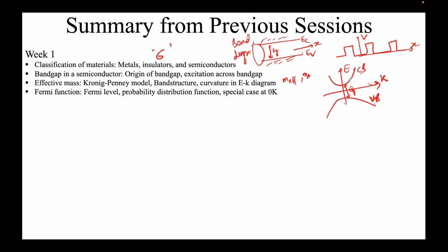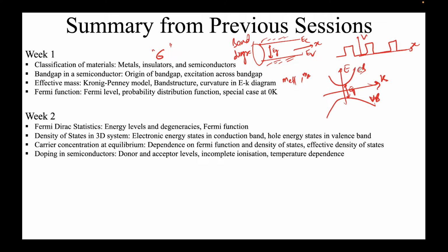And these are just the states that are there. However, an electron has to occupy them. This is where electrons can reside, but it's a probability of occupation. We saw that through the Fermi-Dirac statistics, which are followed by fermions, that is, half-spin particles. The electrons reside based on this probability, f(E) equals 1 over 1 plus exponential of E minus EF over kT. At E equal to EF, the probability of occupation at energy E is half. This theoretical construct is supposed to be the Fermi level.